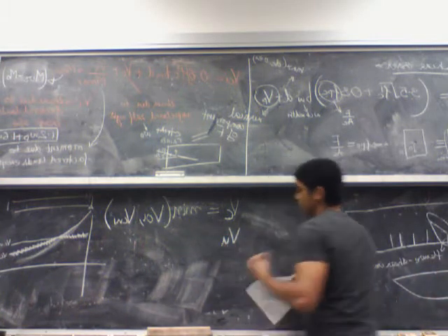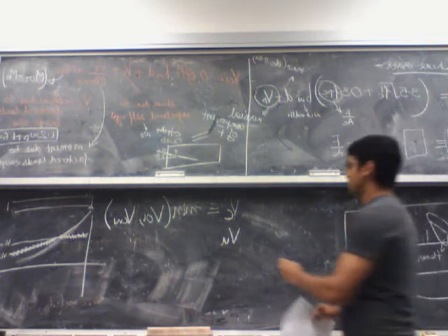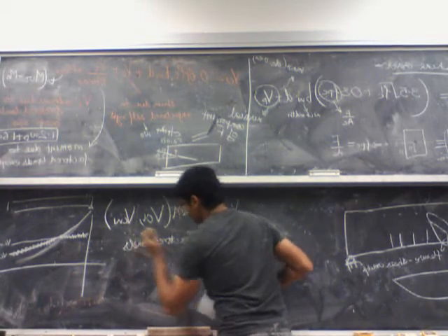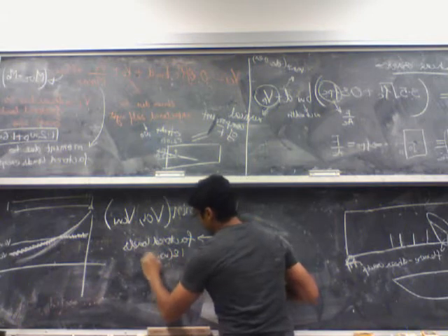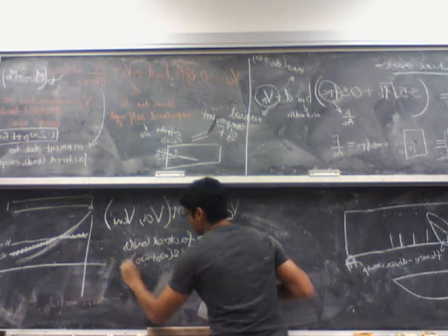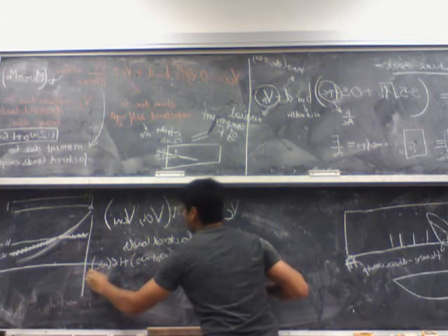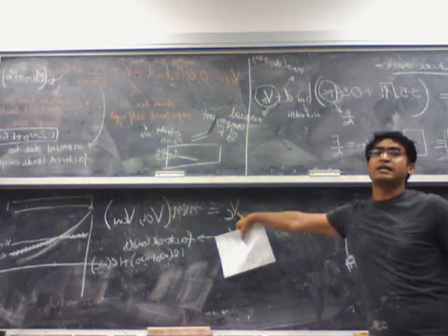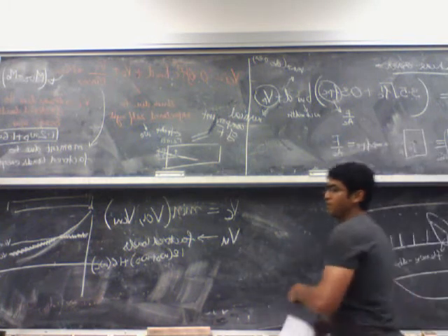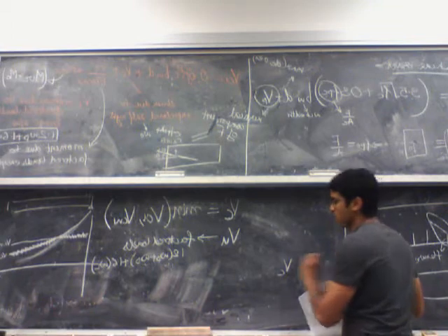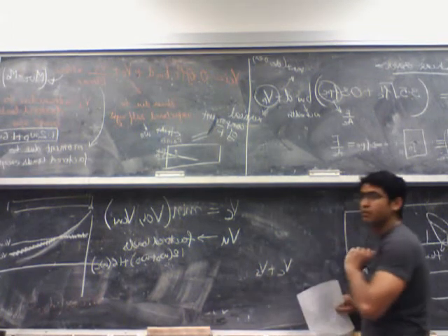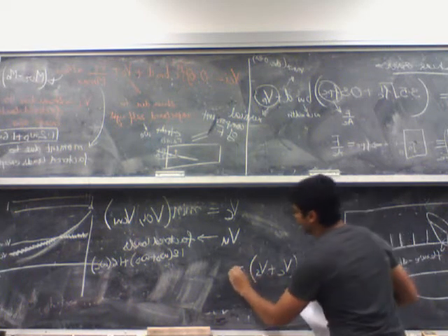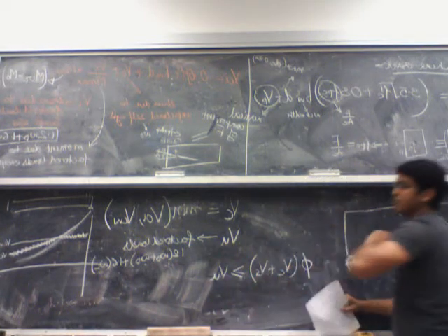You know the shear demand throughout the length, which is based on factored loads. So it's 1.2 times self weight plus dead load plus 1.6 times the live load. So this is my demand. This is the shear capacity of the concrete itself. What is my total shear capacity if I also have stirrups? My total capacity is the capacity of the concrete plus the shear capacity of the steel. This is my total nominal capacity multiplied by phi. This has to be greater than or equal to my shear demand, which is VU.